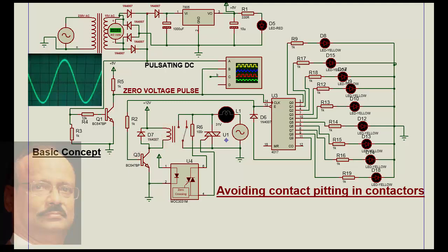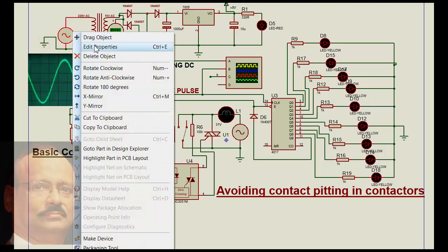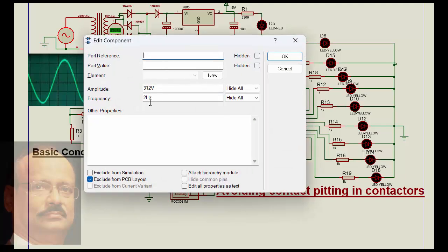Now let's watch it. Now see, the lamp is on. The relay contact has not taken over. Now the relay contact has taken over after the counting is over. We have deliberately done it at a lower frequency so as to see this clearly. If we change it to 50 Hertz, we will not be able to see it, because it will be doing so fast. Now we have taken it at 2 Hertz.